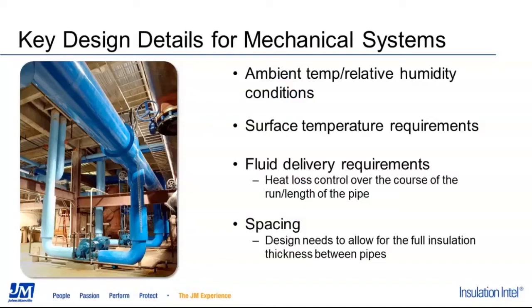Next, surface temperature. It should be less than 140 degrees Fahrenheit for the hot system, and that's per OSHA. Sufficient amount of insulation is required in order to achieve this condition, so the correct amount should be specified.